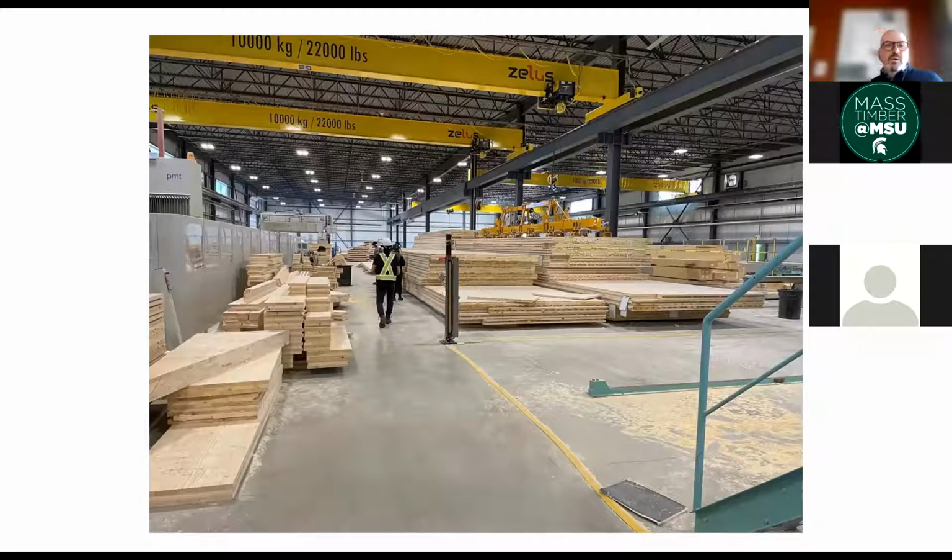This is a photograph of about the last 25% of our plant, already past the equipment that manufactures this. This is kind of like our fabrication end of the plant. And the panels that you see there on the right, these are the panels that were used in the YW project. They've just come off the line. And so what we do is we pick them up with the overhead gantry that you see there, and we move them to the left where you see a little bit of our CNC equipment. And there we trim off the panels, we pre-cut all of the window and door openings. Usually there is a BIM model for this where we're integrating the mechanical systems early into the design of this.